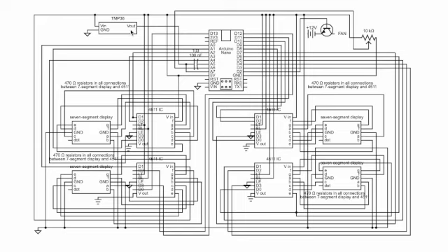Inside this circuit, there are 2 inputs, one from the TMP36, while the other is from the 10K ohm potentiometer. The potentiometer is used as a variable resistor in order to give the user a value that they can change to set the temperature to their own liking. The output from the potentiometer is connected to the Arduino Nano, which takes it in as a value that is then mapped to a number from 0 to 99 from the original value range of 0 to 1023.